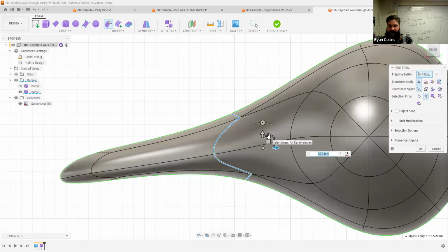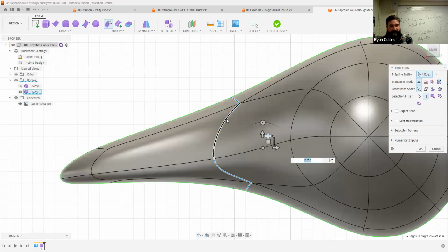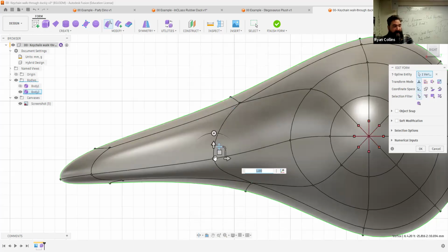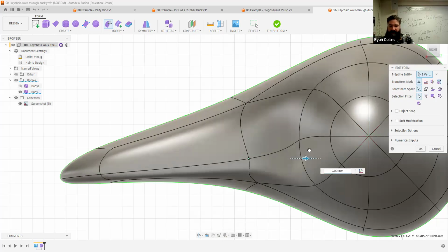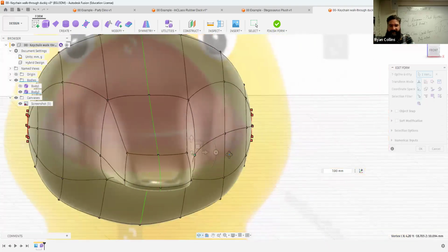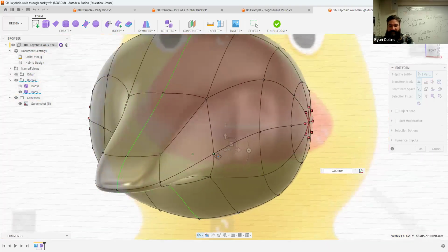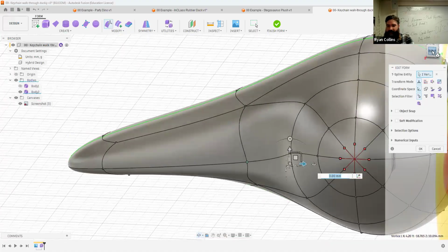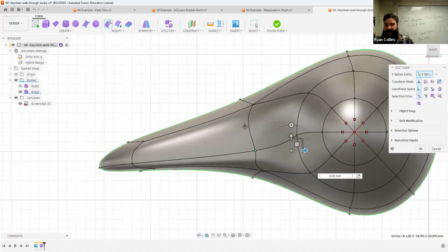Oof, this is quickly becoming unsettling. So, there we go. I'm attempting to straighten this back out, not doing great. If you are trying to isolate some elements, it might actually be better to switch to vertex. I'm just going to select that one vertex and drag that backwards, trying to align these a little bit. You can see what's happening to the face. Ooh, this is becoming not a duck very quickly. Whatever. It's a plague duck. Exactly. Plague duck it is.